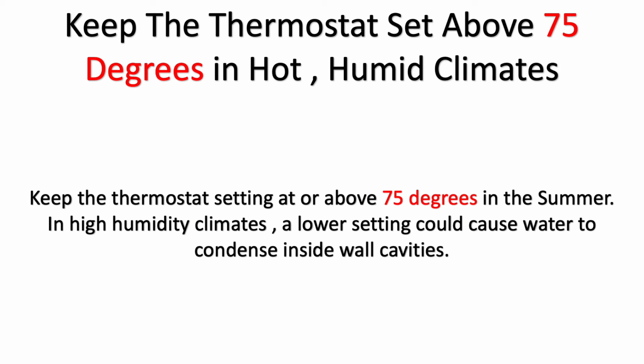Keep the thermostat set above 75 degrees in hot, humid climates. Keep the thermostat setting at or above 75 degrees in the summer. In high humidity climates, a lower setting could cause water to condense inside the wall cavities.